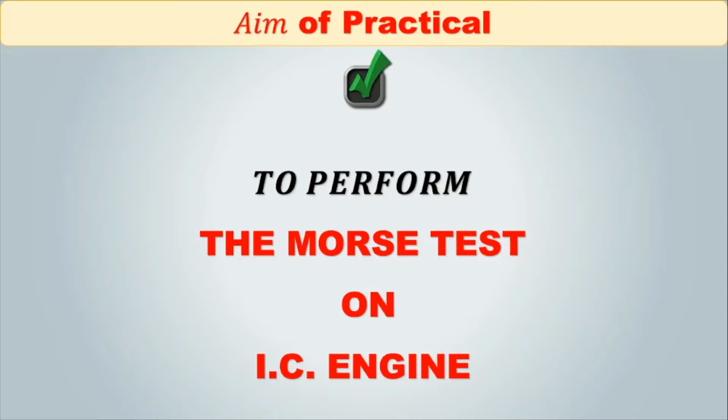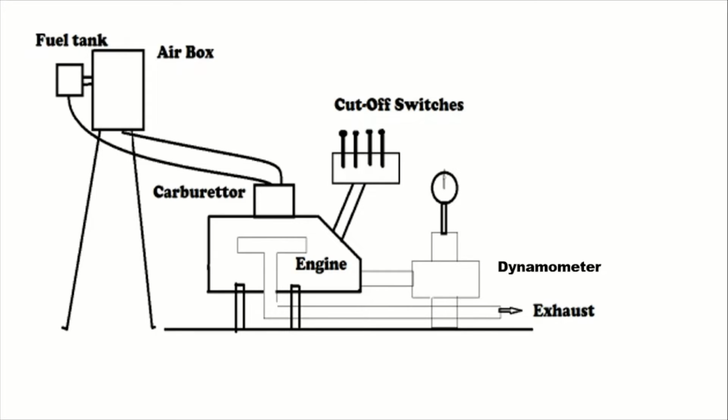The aim of this practical is to perform the Morse test on an IC engine. Here is the schematic diagram of the Morse test. The purpose of the Morse test is to obtain the approximate indicated power of a multi-cylinder engine.